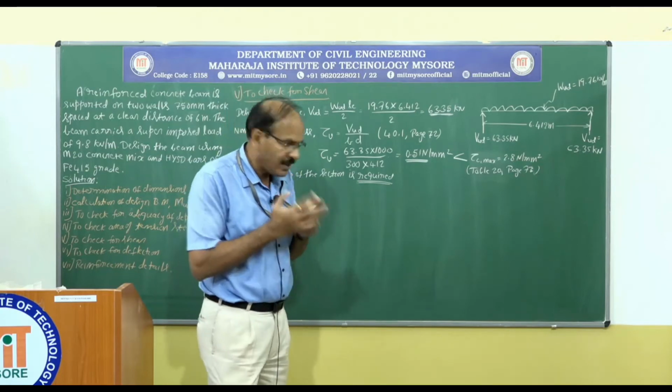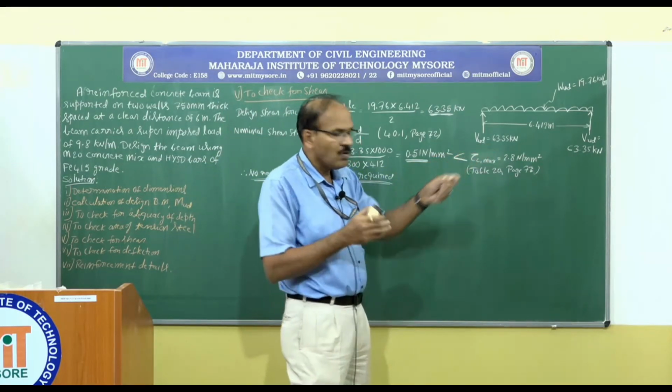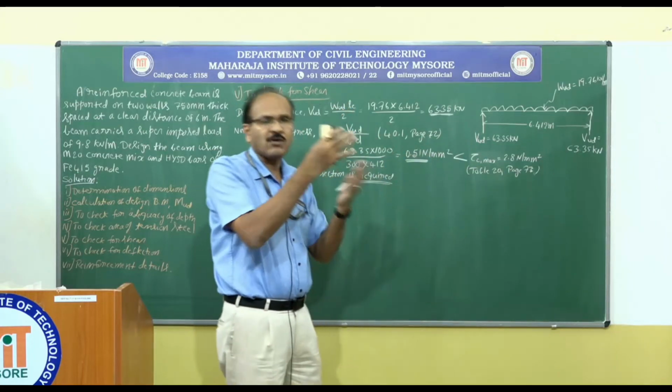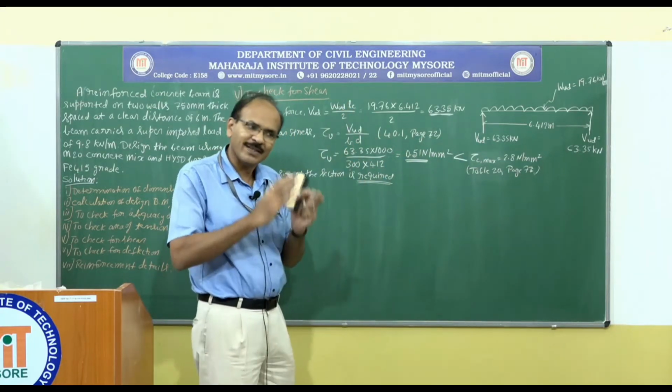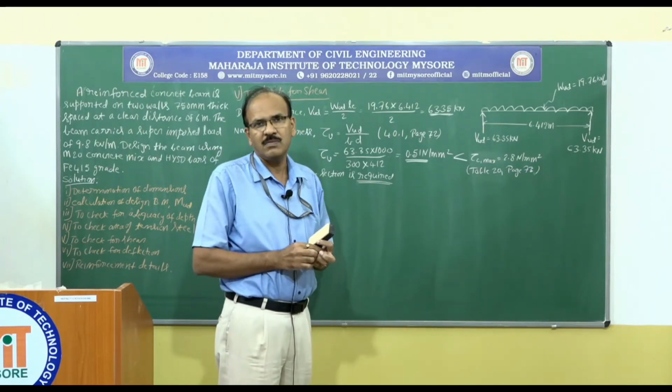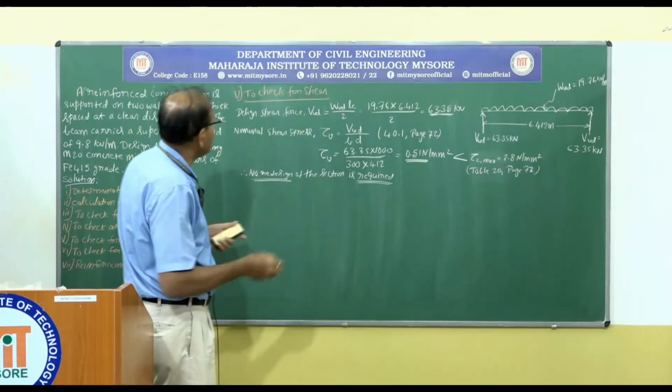That value is compared with this. If this value is higher than the concrete capacity, then for the remaining load we are going to provide stirrups.